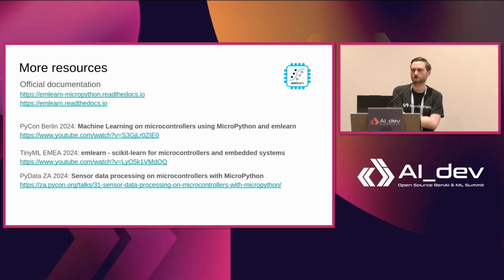Yep. And is that example in the limit of what's acceptable for a microcontroller? Yes. The question is, there was one example shown with object detection of a cat. Is that doable on microcontroller grade, or where does the limit typically come in where you want to go to a bigger system? So yeah, you can. I think for the smart doorbell, you probably don't need object recognition. If you position it well and design it well, like you have a cat hatch or something, you could just do all the image classification. That would work super well. You don't need high frame rate or super high resolution to recognize a cat.